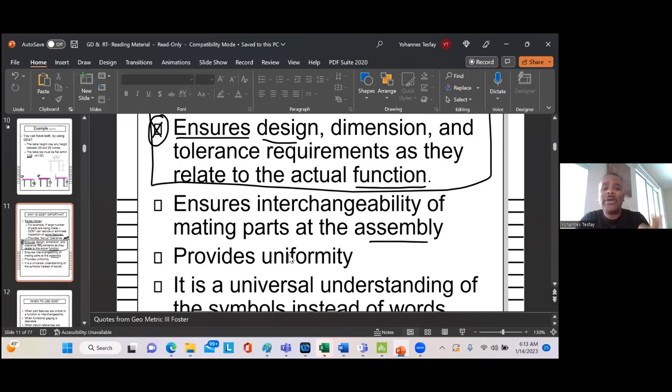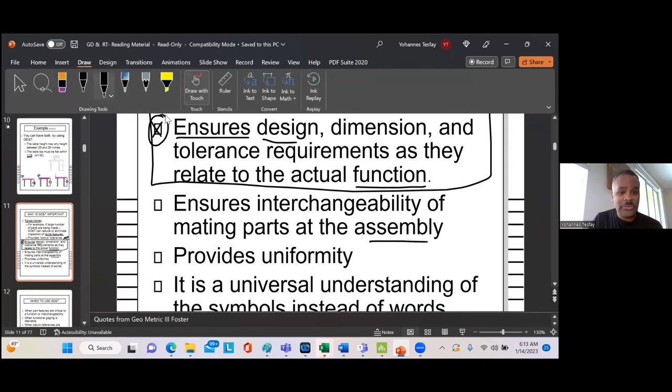And also the other factor right here might be roundness. So the things we called diameters here might not be circles. On one side they may be very large and on the other side very small, so that also creates extra friction. Friction increases. So if it sticks like this, we go and check those features. That's what interchangeability means. It's one of the most important aspects of GD&T